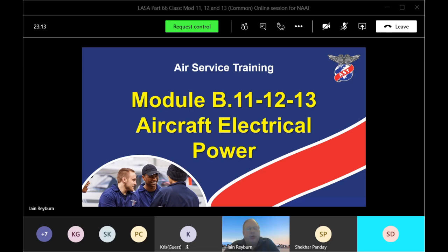And the back EMF is trying to stop the relay from de-energizing. What it'll end up doing is this coil will produce a positive here and a negative there. But because of this diode, that current will flow through the diode rather than the coil. So it's a bypass, it's a short circuit. Otherwise my relays don't come down cleanly. They can chatter, and that can cause damage to the system. So what's the purpose of the diode across the energizing coil in a power contactor? It is to stop what they call power hold on or relay chatter. So it short circuits the current going across the coil.